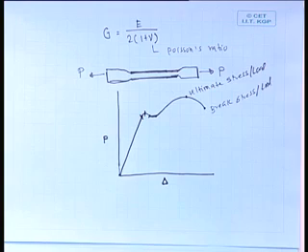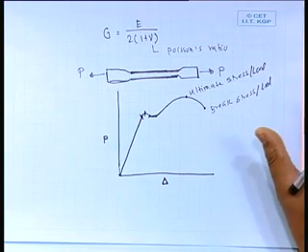So, here what is happening, your area is reducing, load carrying capacity is reducing, but actual stress, if we measure, you will find actual stress will increase beyond that point. But the nominal stress, meaning whatever load divided by the original area, that we define as nominal stress. That nominal stress will appear to be reducing. Anyway, that will be the behavior of the stress strain curve of a mild steel specimen.